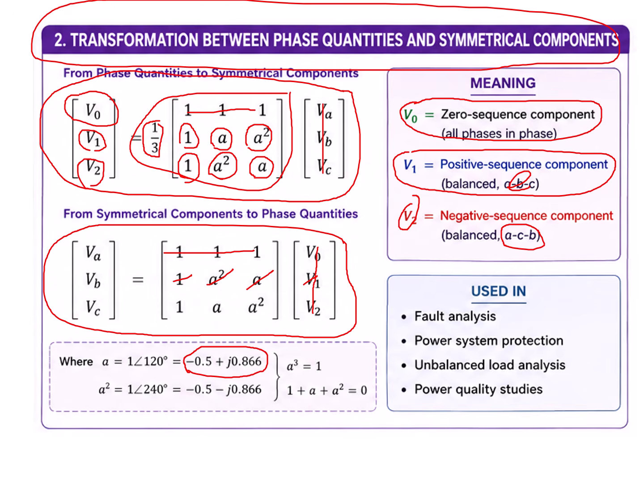If our system is supplying a motor, the motor is running in the normal direction and a fault occurs, our voltage will have positive sequence, zero sequence, and negative sequence. Positive sequence is trying to push the motor to run in the normal direction, whereas negative sequence will run the motor in the opposite direction, because phase reversal is used to change the direction of motor rotation. So this creates two opposing torques in the motor, and will create a problem, especially in the heat industry.